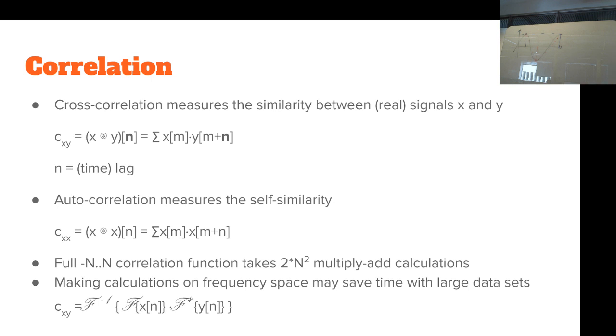So this takes quite a lot of time actually to do all the calculations. With 1000 points, for each point here you do 1000 multiplications. And if you want, say, 1000 time delays here, then you need to calculate 1 million multiplications. But calculations are cheap. Just add power to the processing, and that's it. Just add money. Yeah. And autocorrelation, as I said, is just measuring one signal and calculating the similarity of the signal to itself.